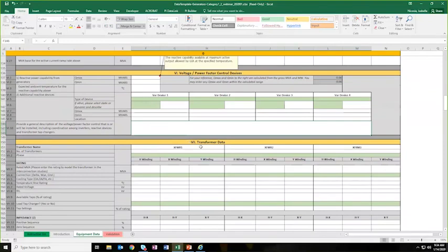Also, if you have a power plant controller, that controller will first switch capacitor banks in and out. It may also adjust the transformer tap changes, and it coordinates the generator Q output. So put as much information as you can here, as it helps us understand your dynamic model and evaluate whether your plant is meeting all the performance requirements.